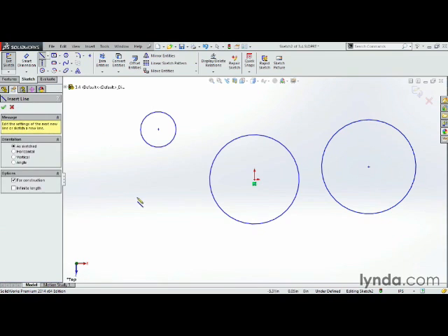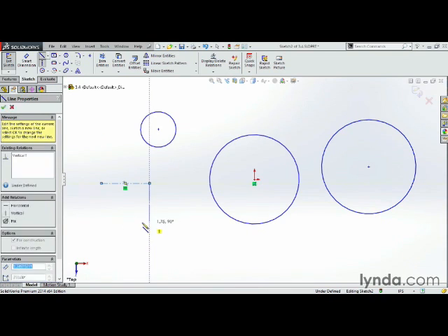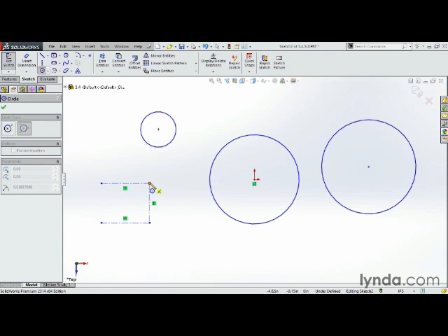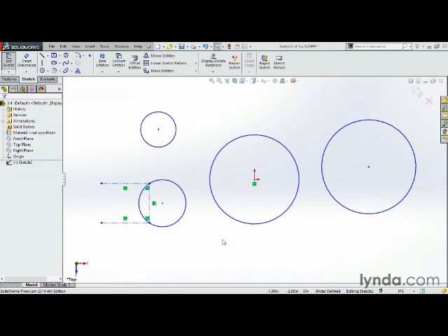For instance, if I have a couple center lines that are in my design, and I want to put a circle here, I can choose a perimeter circle, pick one of the corners, pick the other corner, and I can define how I'm going to place that shape between those points. It's a really handy way to easily create geometry and circles using a simple couple commands. The circle tool and the line command are the 2 sketch entities used most to build geometry in SolidWorks. Mastery of these tools is essential to being proficient in SolidWorks.